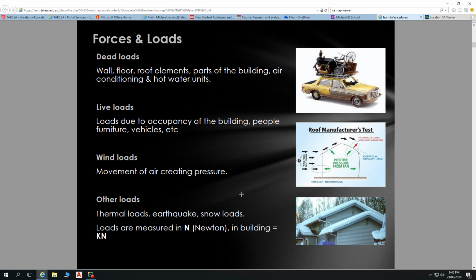We don't have any sheet bracing on this, but it's fairly simple to understand. A piece of sheet bracing, OSB board nailed on there. Sometimes you can increase your kilonewtons of bracing by including rods going from top to bottom, tying the top plate into the floor structure to provide that extra vertical restraint that works in concert with that sheet bracing as well.